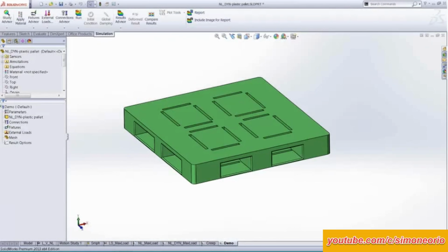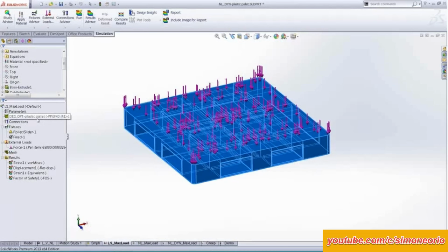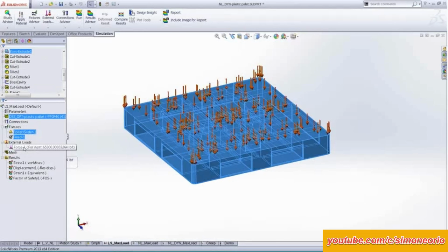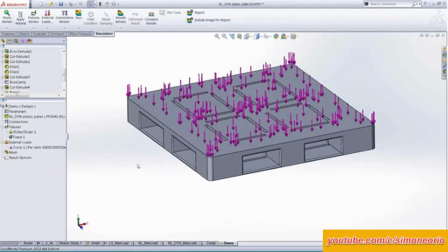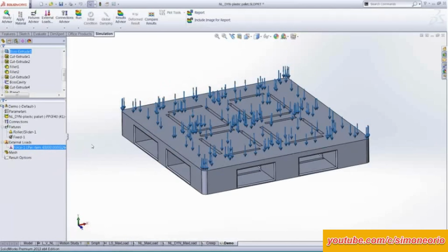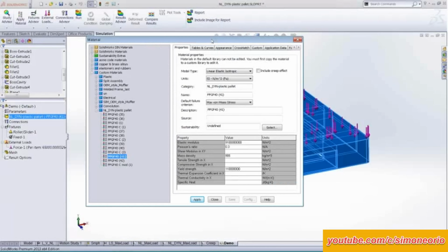And you'll notice that even though we're doing nonlinear analysis, the feature manager looks very similar. And what's really great about being in SOLIDWORKS is I can actually go back to my existing study and grab my fixtures and my forces and drag those over. And now I have most of my model already built. My forces are applied to the face, but now all I need to do is go in and modify my material properties. So when I right mouse button, apply, edit my material,